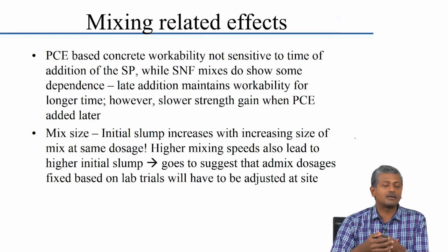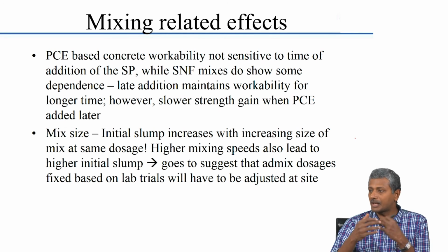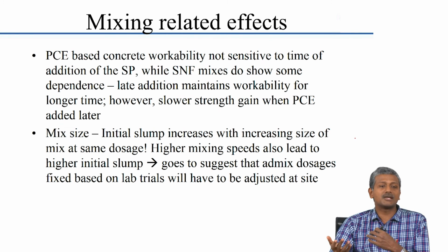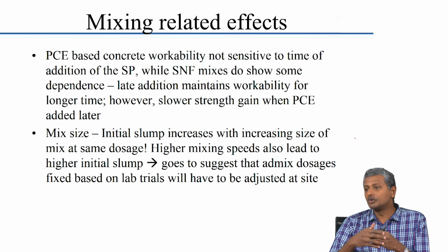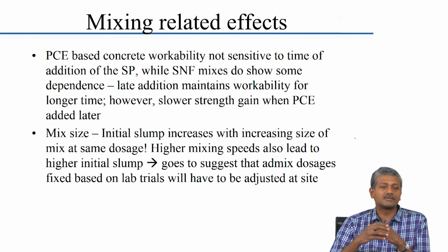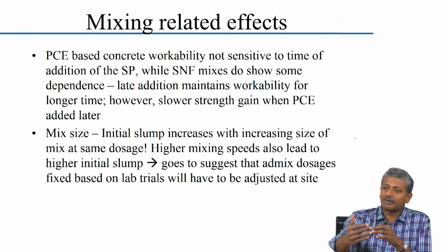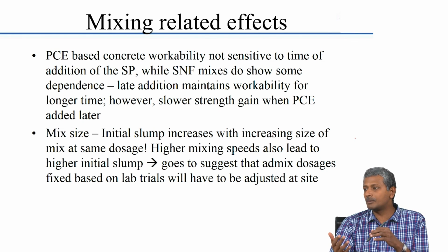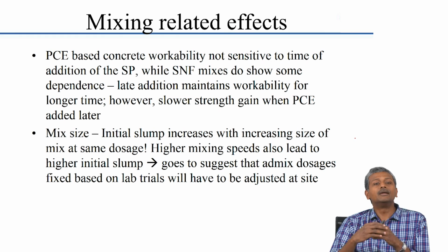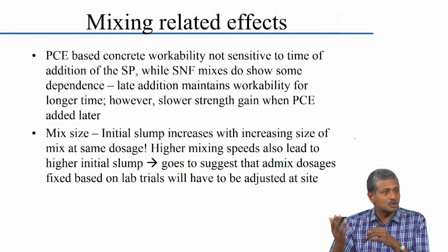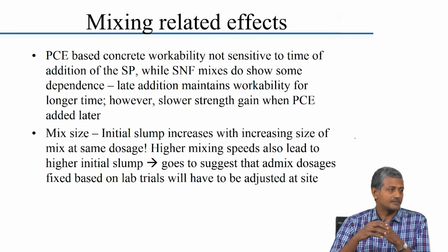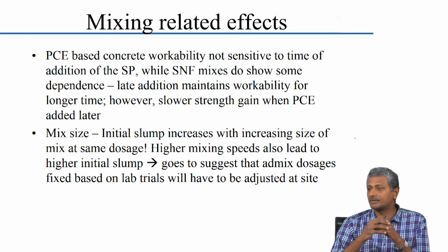We are doing all our mix designs for field applications based on lab studies, but what I am just trying to say is very often it helps to do an actual field trial before you completely fix on your superplasticizer dosage. Okay. That is one thing you need to leave to the field trial stage to ensure that you get the required workability and retention based on the type of mixing equipment and mixing durations that are going to be used at the site, and do not always rely on laboratory data in the case of SP dosage. That is where we need to be extremely careful.